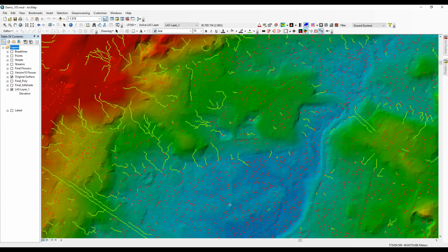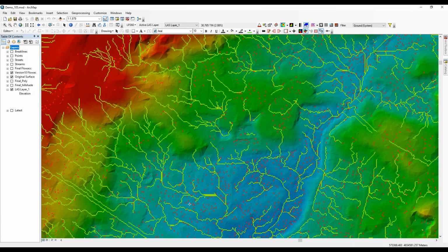So one of the first things that you'll notice is all these little red pixely dots all over the place. And these are what we call sinks, right? This is an area where on the surface model, the cell doesn't know where to go. There's no downstream cell from that cell, so we can't accumulate flow downhill. It happens a lot in flat terrain, and in LiDAR data, just because of the roughness of the surface at this fine scale, we get millions and millions of these sinks. So we have to judiciously start to fill these sinks in without negatively or artificially affecting the flow field. As we do that slowly, we start to be able to accumulate flow downstream and see where the flow is going to go.